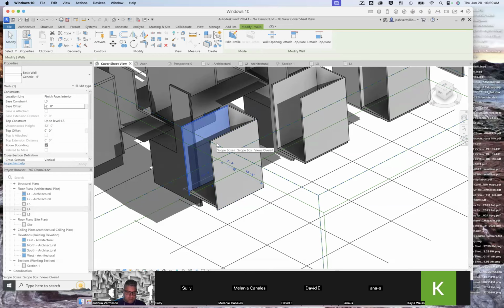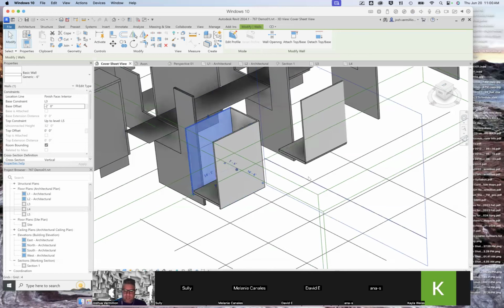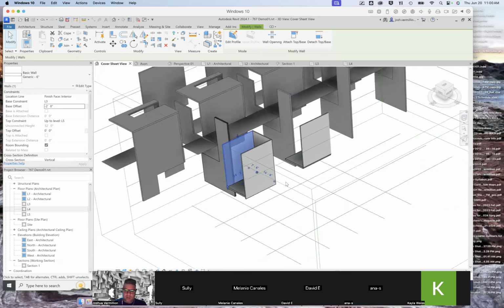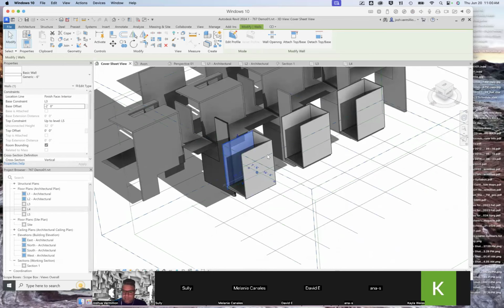I'd want a parapet and some flashing, and then a flat roof isn't really totally flat. You'd probably bring it back to some scuppers or something in the side, right? Or a gutter or a drain, depending on how big the space is and if there's structure moving through it or not in the center. So anyway, long story short, I would do that with all of these.